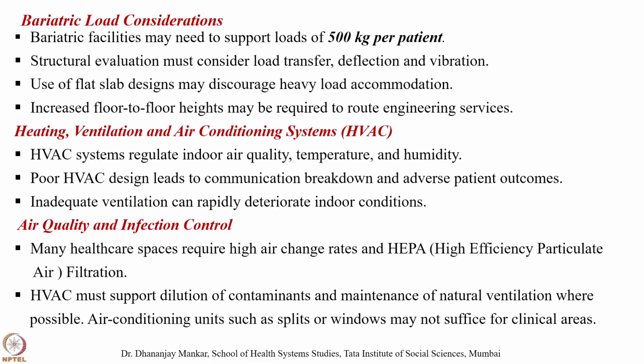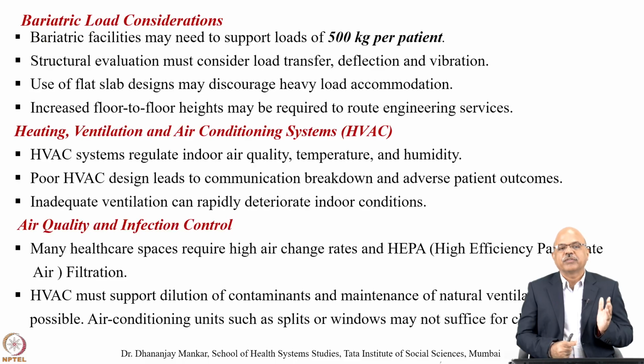What is bariatric load consideration? When we talk about facilities which need to support loads of 500 kg per patient, the structural evaluation must consider load transfer, deflection and vibration. The use of flat slab designs may discourage heavy roll accommodation. Increased floor-to-floor heights may be required to route the engineering services.